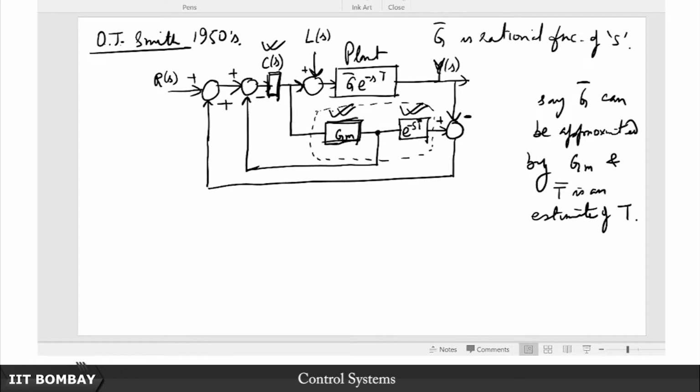So now that we are faced with this, what is the transfer function G(s) equal to Y(s) over R(s)? That is what we want to evaluate, and then we also want to evaluate G_L(s), which is basically Y(s) over L(s). Okay. So, what we want to do is find out what these two transfer functions will be. We want this transfer function to tend to unity, for maybe, let us say, a step input.